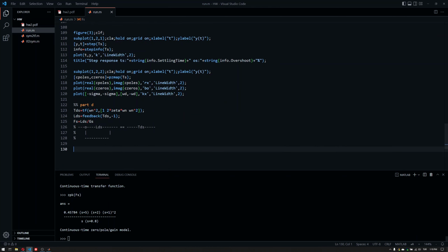The only problem here is that if we have a modeling error, that will cause some problems because the cancellations will mess up. Once that's done, you will just end up in weird behavior because you are relying on too many pole zero cancellations. If you think about it, the model should be better than perfect because you have too many cancellations, namely four. You are canceling four poles and zeros. They should all be on top of each other, which is not going to be the case, ideally.